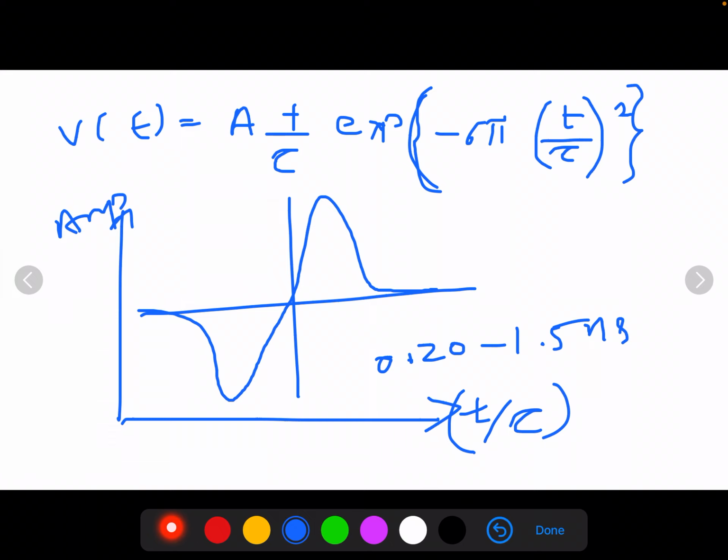To transmit a binary symbol 1, the pulse is transmitted slightly late, plus Tc. So the receiver detects this early or late timing and demodulates the data accordingly. The separation between the pulses Tp, which ranges from 1000 nanoseconds to as little as 25 nanoseconds, results in data rates ranging from 1 to 40 megabits per second.